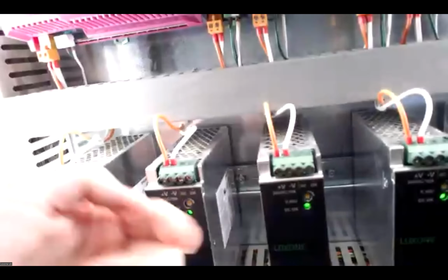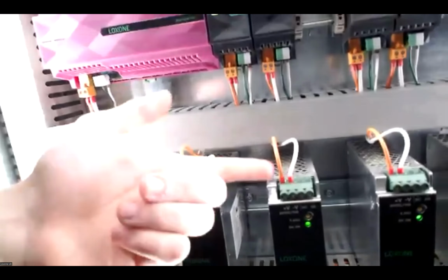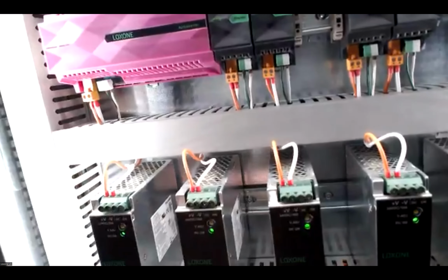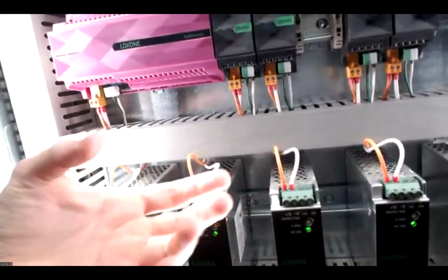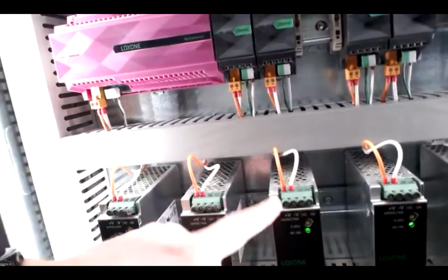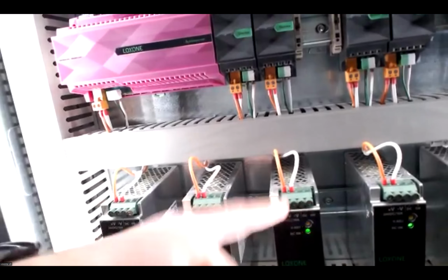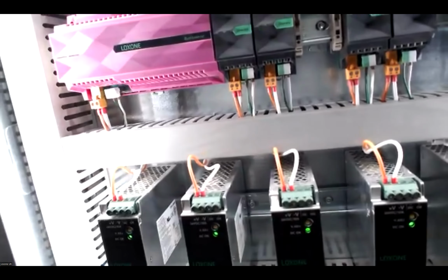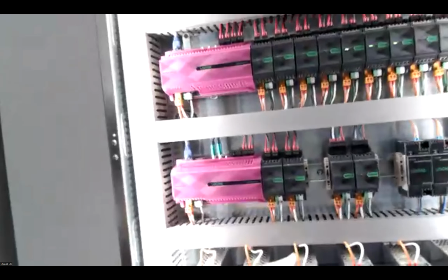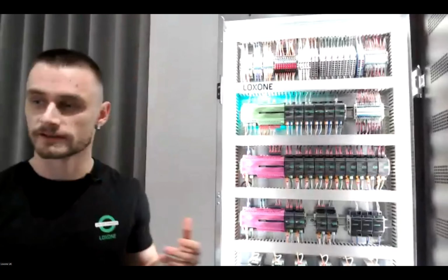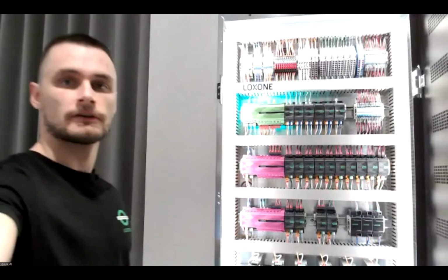Then, as you can see, they have ferrules. Because these ones are stranded core, this is a stranded core cable. Because of that, you always want to have a ferrule, especially in a screw-in terminal block or a screw-in Phoenix, like this one is. Now, from here, we're going up and we start going to different devices. Let me go with a few recommendations of things that we can do and improve.